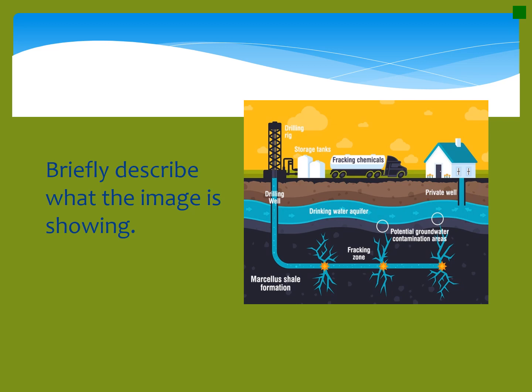So let's try to explain once again what is happening during fracking. Okay, so this is a fracking one. What you're going to do is you're going to drill down. Then you are going to put your pipe, once you find the nice layer of bedrock, you are going to go and do a 90-degree horizontal pipe. Then you are going to do your perforations, which is basically holes in your pipe.